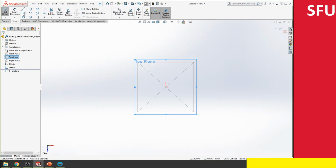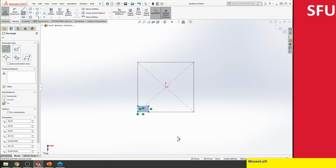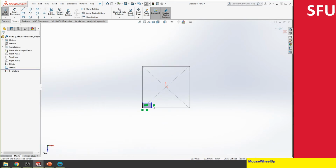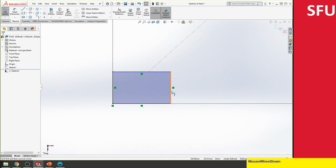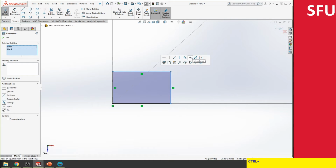And then here I'm going to create my center, or I can actually do it on the edge corner rectangle. So I can choose this to be one of the corners. Since I want it to be square, I can choose this and then set the square as one of the constraints. So let's zoom in here. I'm going to select this guy, and then make them to be equal.